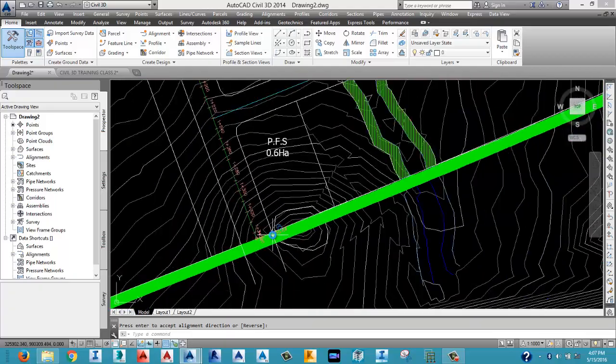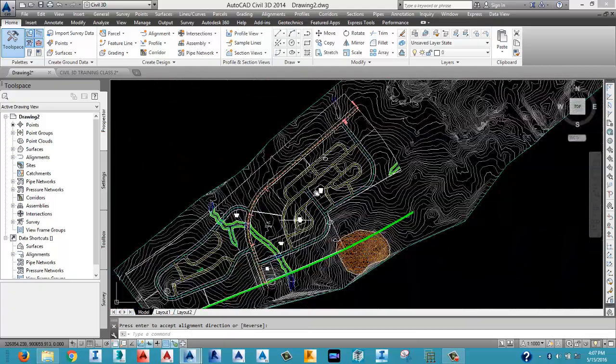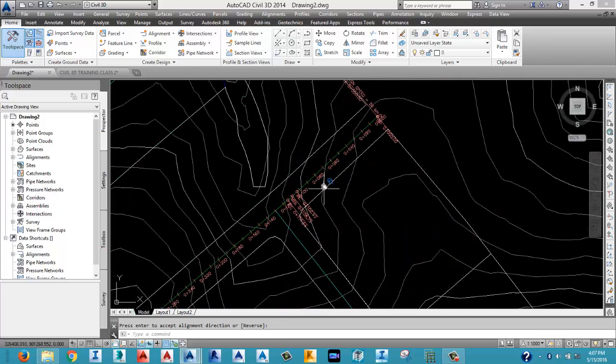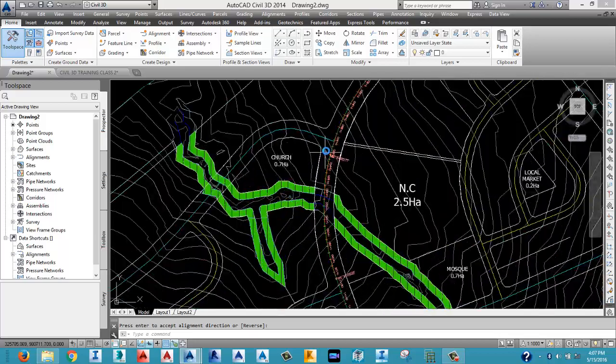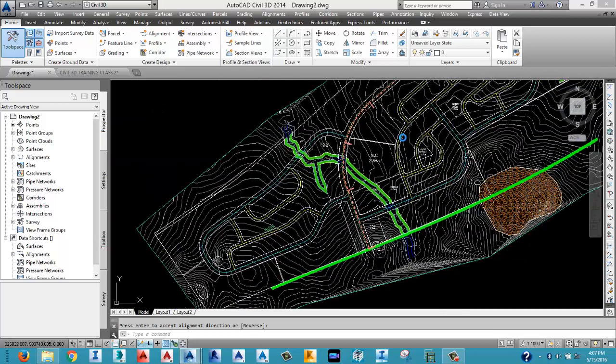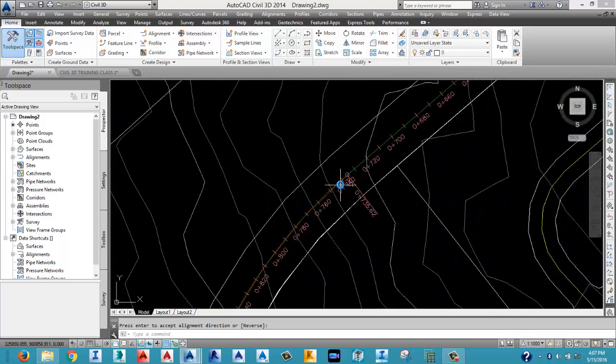So you cannot drive above 56 km/h? No, it's not like you cannot drive above 56. The road is designed in accordance with 56 km/h. If you are driving and speeding over 56 km/h, you know where you see the effect is when you get to this curve, because you tend to see your car skidding, like you want to skid off the road.